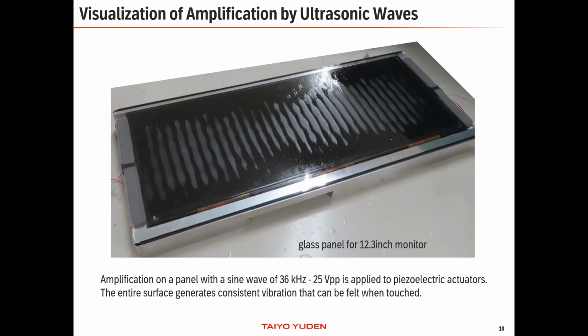This picture shows the visualized amplification on a 12.3-inch panel with liquid when a sine wave of 36 kHz, 25 peak-to-peak voltage is applied to piezoelectric actuators. As shown, the entire surface is vibrating, and when touching the panel, uniformed haptics can be felt.